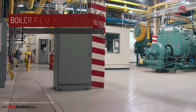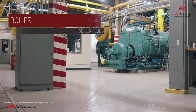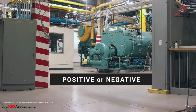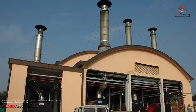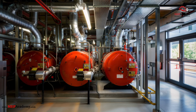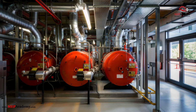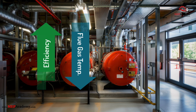All certified boilers have a uniform test procedure to evaluate the vent system. The vent categories are determined to be either under a positive or negative pressure, and whether they have the possibility to condense water from the products of combustion or are non-condensing type boilers. The ability of the products of combustion to condense into a liquid is related to the efficiency of the boiler. As the efficiency of the boiler goes up, the temperature of flue gases becomes cooler, increasing the chances of condensation.